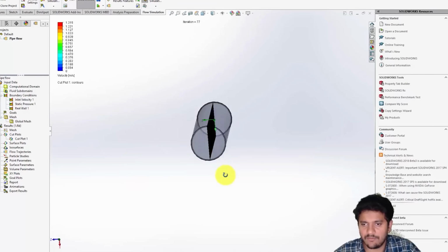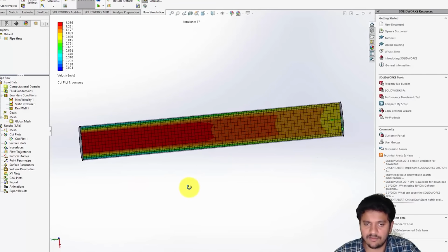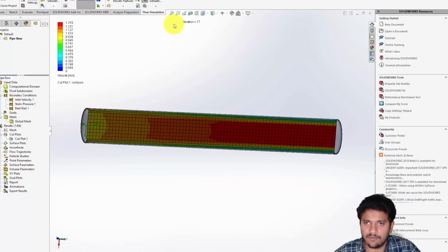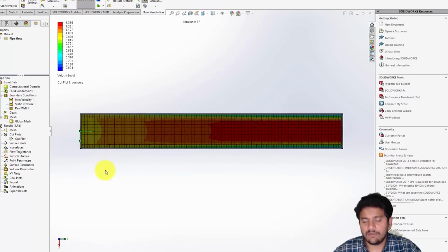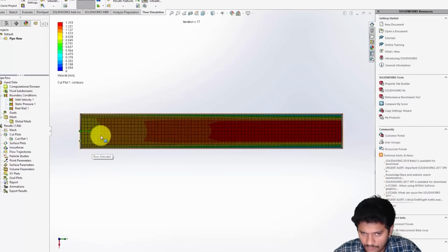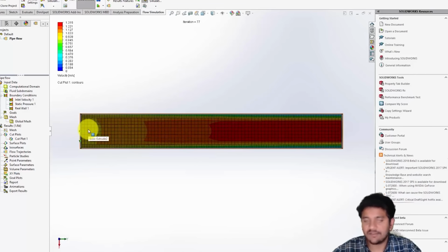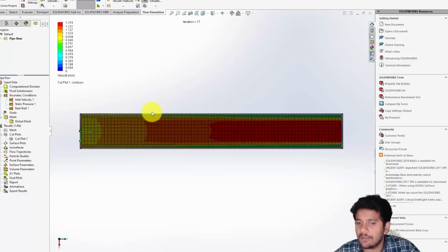And I believe the flow comes like this. Yes. No, actually the flow comes from left to right. Sorry about that. Right, so you can see that the initial velocity profile looks uniform, basically along the x direction. Okay, so if you look here along the x-axis, the velocity is given the same color, right, which means it's uniform. And as I move from left to right, you see the boundary layer appearing, and then you are getting